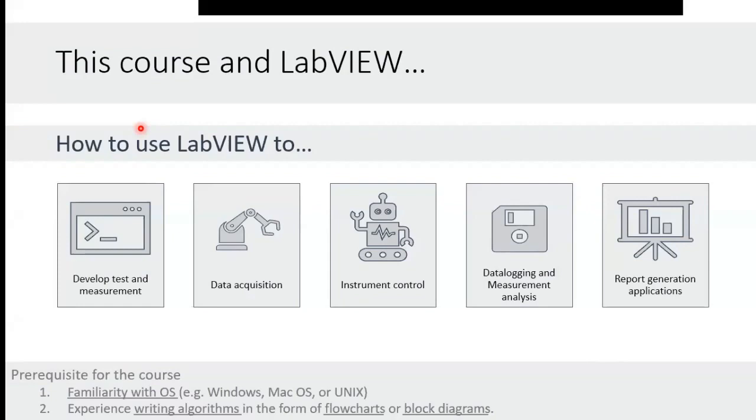If we only acquire the data and see it on the screen, but we cannot store it, then it's no use, right? So there is this step called data logging. Data logging is a term for saving the data into your hard disk. Okay, so we know that in a Word document we can save the data by clicking save. But for an instrument to save long data, big data, we need to do some processing, right? So LabVIEW has another very good technique so that you can do it automatically, many times at the same time, many files at the same time.